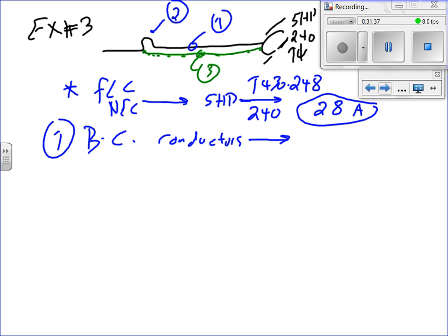It says system voltages range from 110 to 120, from 220 to 240. You see it right above the table? That covers the range of all these voltages. Good point, though. There's no 240 there. There's 230, right? Because the top of the table tells you that's the range we cover. Okay, so everybody knows why we got 28. That's very important. Let's go size it.